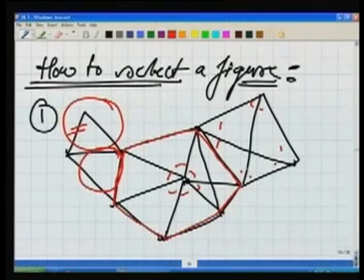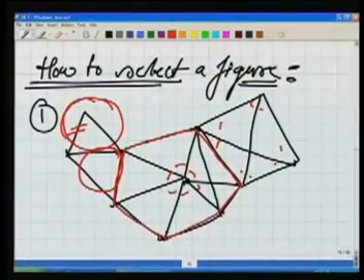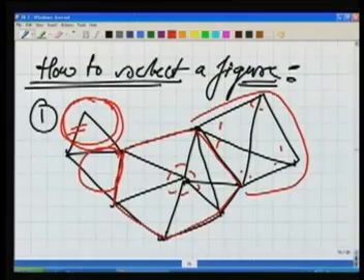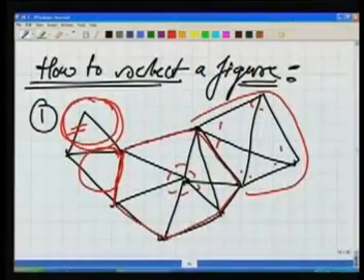So it's a combination of all the figures depending on the field condition, depending on whether you could locate your stations or not. Over here, the requirement of the field was only 3 stations, so you went for a simple triangle. But here you found that you can find 4 stations and the requirement was like that, so you went for a base quadrilateral. So your figure could be anything.